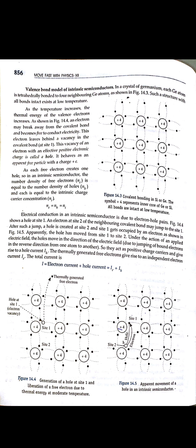Holes are nothing but a vacancy or interstitial space given out by the electrons, and this space is almost filled by the electrons themselves. So they are positively charged. We just maintain that the electrons are leaving from there, or there is a deficiency of negative charge, that's why they should be positive. We are assuming it. So we know that the density of electrons and holes is the same in a pure semiconductor, because we are not adding any kind of impurity.